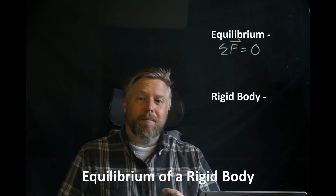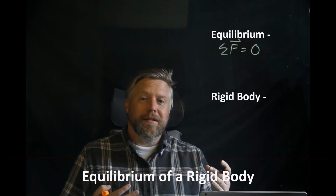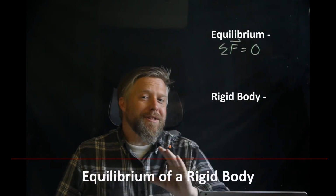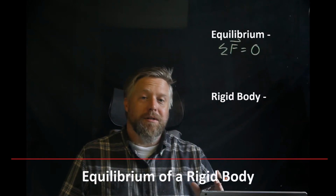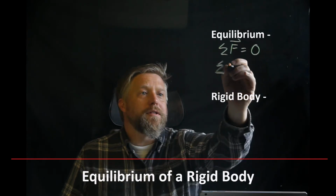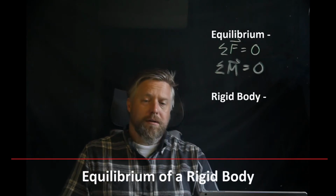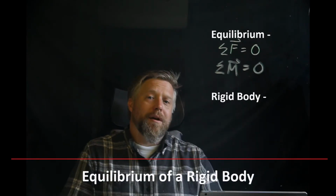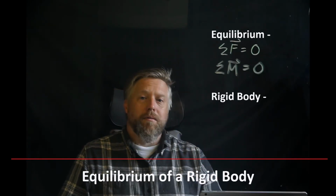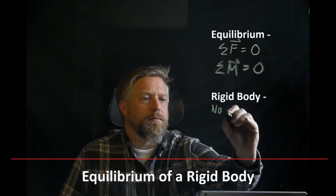And what have we learned so far about that? Well, we just learned about moments. We learned that if a force is applied at a distance, it creates a twisting that we call torque or moment. And if an object's not moving, all of those moments have to be 0. Otherwise, it would be twisting. So now, not only do we have the sum of the forces, but we also have the sum of the moments equal to 0. And that is also a vector equation. I'm going to go into that more later as we do our equations of equilibrium. Today, I want to talk about rigid body mechanics. And this is really, we're just getting no more particle.